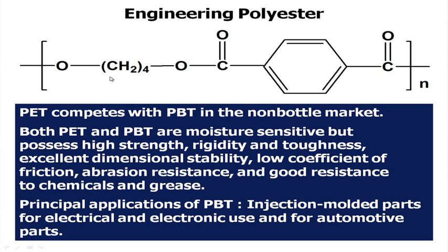Now, let us look into their properties correlating with their formula and structure. Both PET and PBT are moisture sensitive because of the presence of this ester linkage, but they possess high strength. They are rigid due to the presence of phenyl ring, and this polymer becomes tough. Toughness property is good because of the presence of these methylene units, which are flexible. Flexibility is offered by these methylene units and rigidity is offered by this phenyl ring.